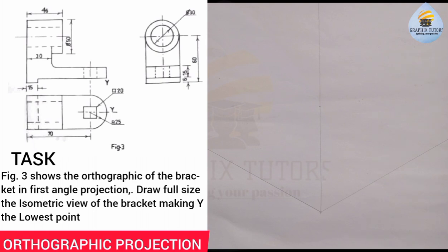Then to get the width, the width is at this side here, almost the smallest part. So the question is, how can I get the width? From the plan. That means from here to here is the width, and the width is given. Is the width given? Yes, it is. It is the radius of 25, which is 50 diameter. So the width is 50.